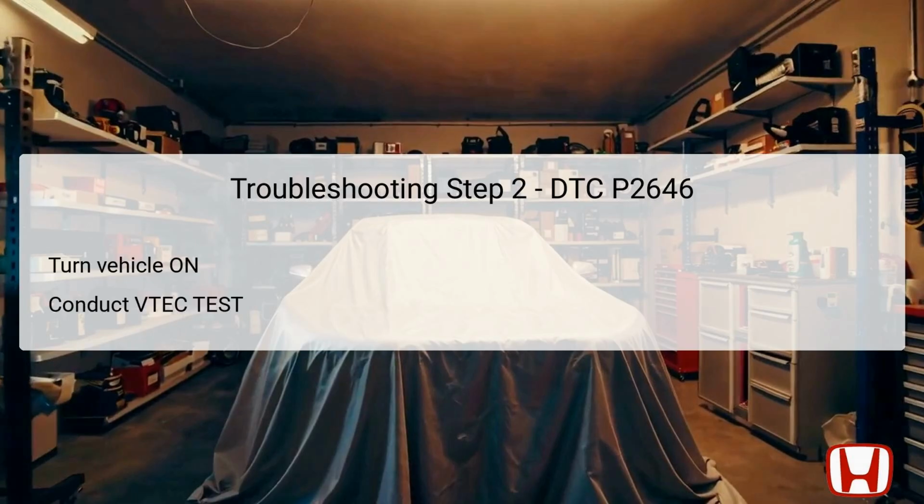The next step requires the technician to turn the vehicle to the on mode and proceed to clear the DTC using the Honda Diagnostic System, HDS. This process will reset the fault codes stored in the vehicle's onboard computer, allowing for a fresh check on the system's functionality. Following this, the VTEC test should be performed via the HDS, which assesses the operation of the VTEC